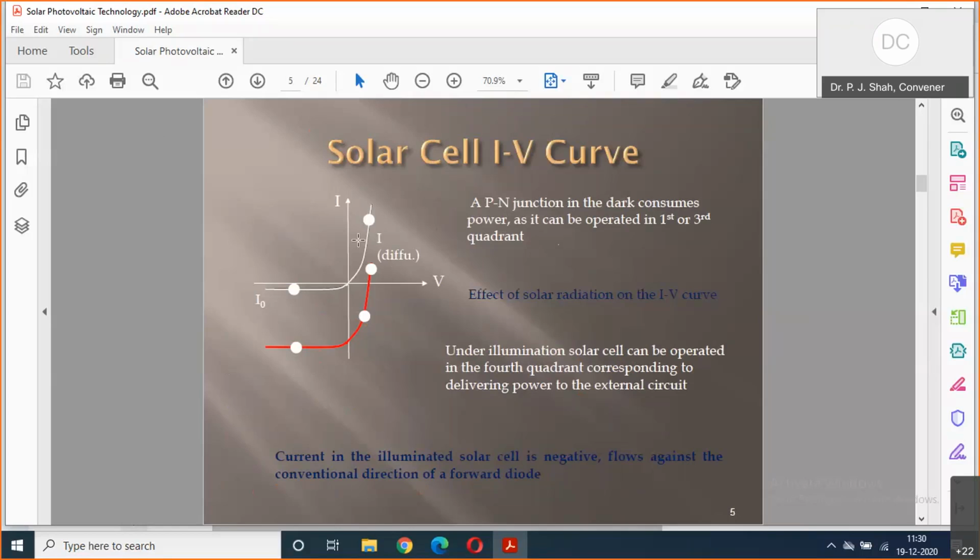Okay. So now you can see that at zero voltage there is no current in a diode. But when you increase the voltage, exponentially the charges diffuse across their respective junction. So there is a linear increase in voltage and an exponential increase in current. That is the diode characteristic.